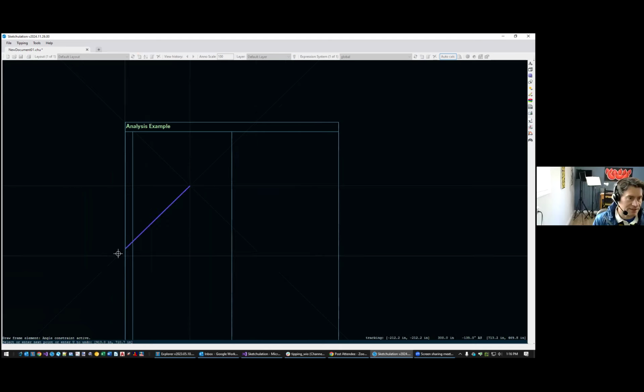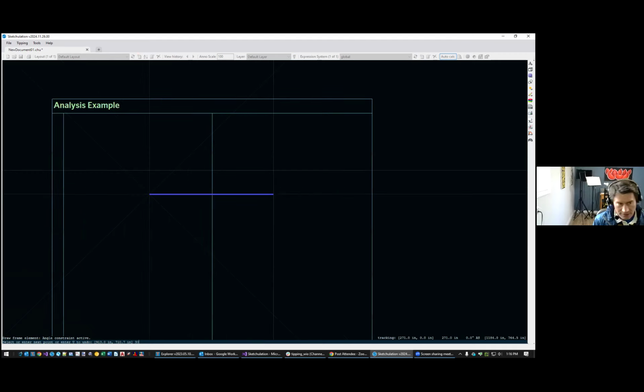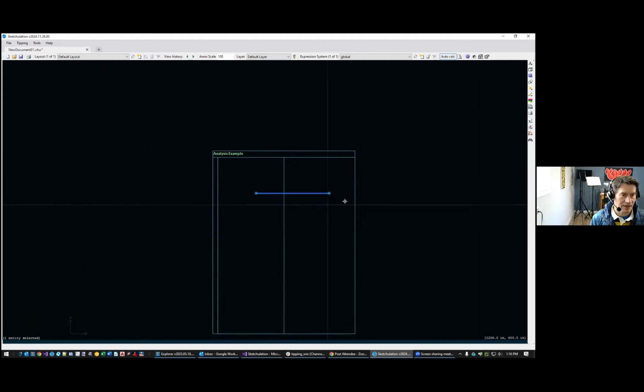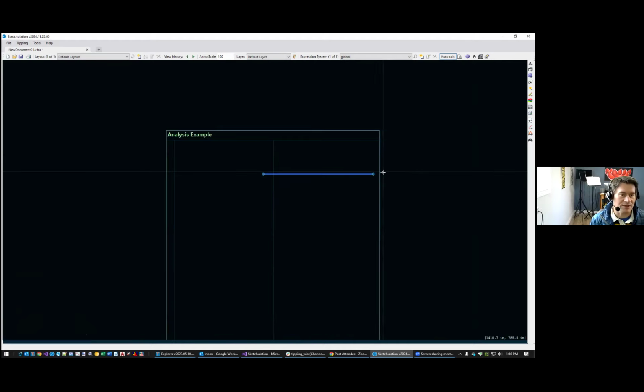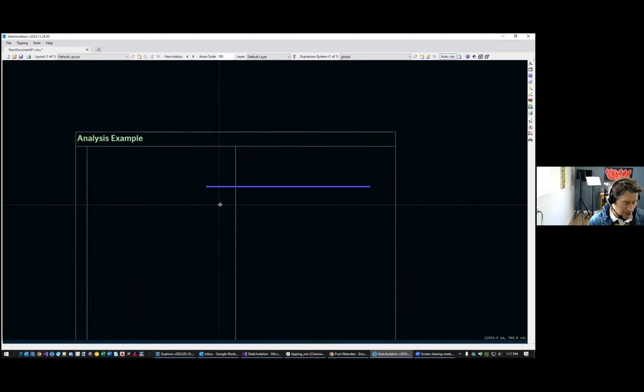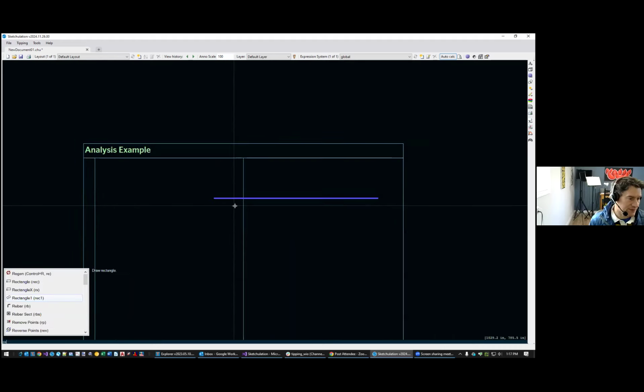I start to draw this. I push F8 to get into the angular constraints. I push 30 and apostrophe for the feet, and it lays out a 30-foot long beam for me. I look at how that lands on the page, and I feel like that's pretty good in terms of how it sits on the page. So I feel like my annotation scale is all set. I don't need to change that. Now we're going to draw in the restraints at the two ends of the beam. I'd start to type RES, and the shortcut for that would have just been R.